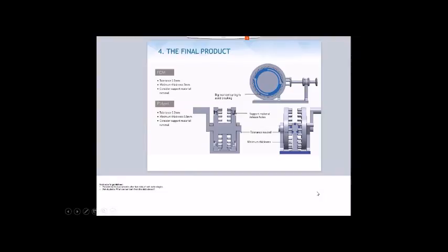And what is most important is the tolerance and the minimum thickness. Consider where to have support. Most of the people who design for 3D printing will say, okay, I will take out the support and this will work. But you need to think about where the support is going to move or how it's going to come out.